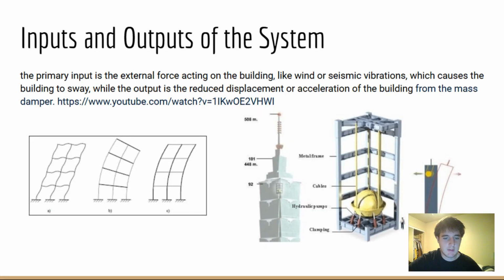The inputs to a TMD system are external forces, like Andrew was talking about, such as wind and earthquakes. The outputs are reduced building oscillations and stabilized motion. Sensors measure displacement, velocity, and acceleration of both the building and the TMD to ensure optimal performance.